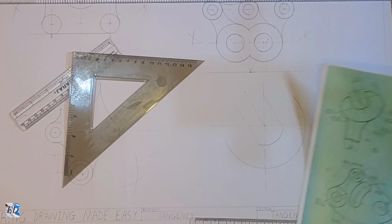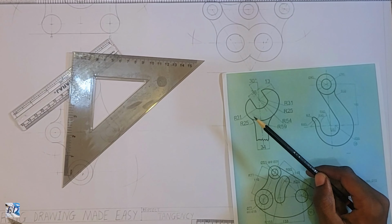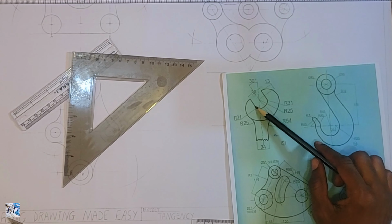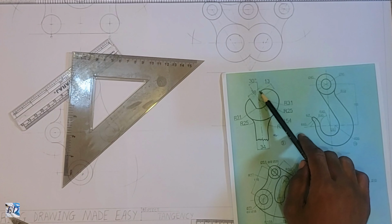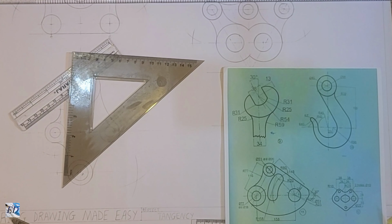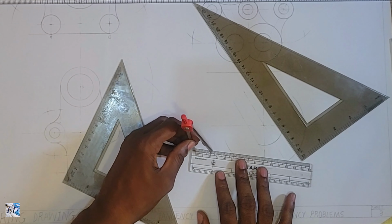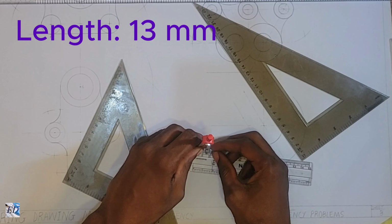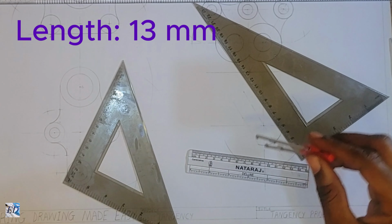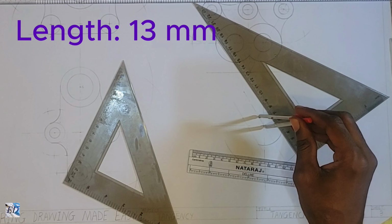Another key thing will be this dimension here. From the center point to this point of the parallel lines is 13 millimeters, right? So we'd have to measure 13 millimeters and then cut the parallel lines off at that distance because that'll be the end for the parallel lines. To go about that, we take our divider, we measure 13, then we mark 13 points on the line.